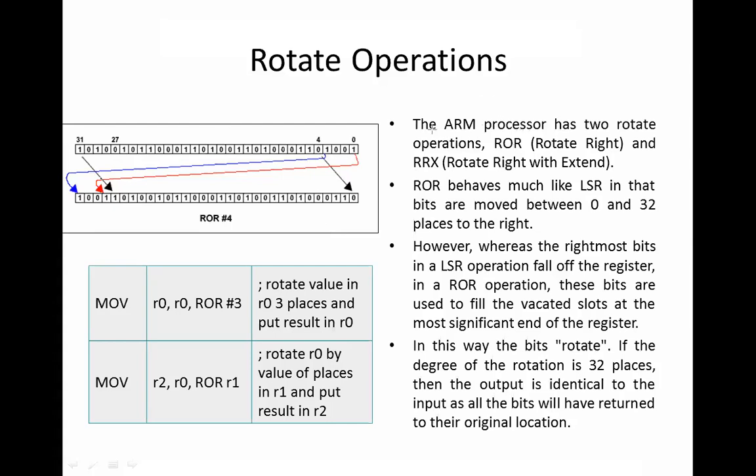The ARM processor has 2 rotate instructions, which are rotate right and rotate right with extend. RRX, X refers to extend.